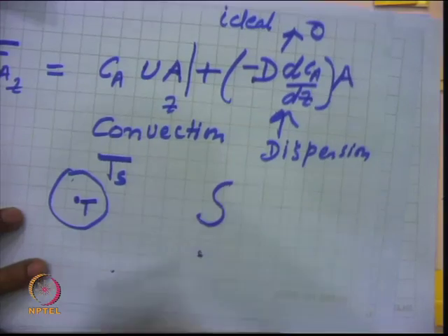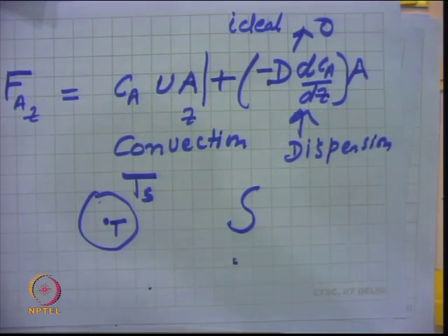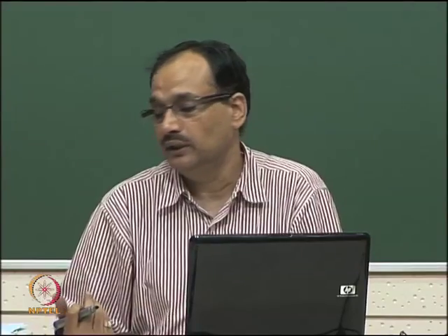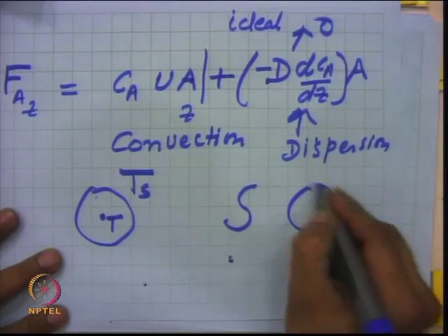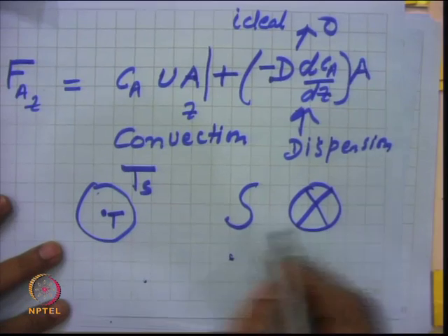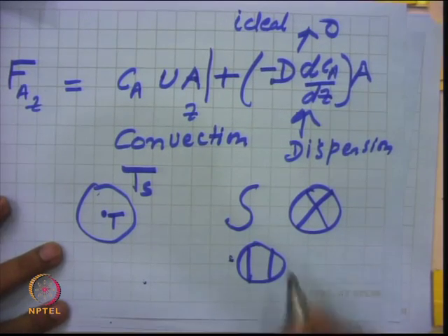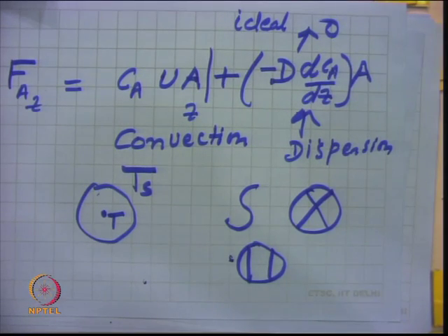The shape of the particle may be like this. In packed bed mass transfer, the Intalox saddles or different types of Raschig rings, and this kind of structures, are used. The idea is to reduce the pressure drop in the bed. The similar thing is done in the case of catalytic reactors also. So, the catalyst selection depends on the size of that catalyst also.